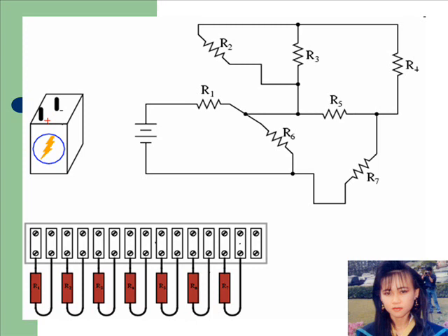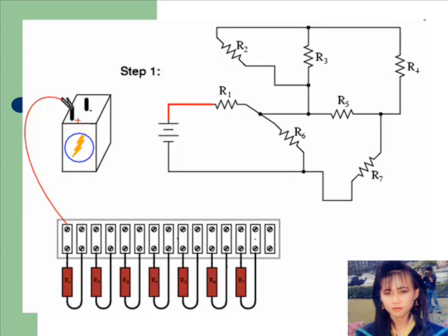First, begin by installing and labeling all resistors on the strip. The original schematic diagram will be shown next to the terminal strip circuit for reference. Next, begin connecting components together wire by wire as shown in the schematic. Overdraw connecting lines in the schematic to indicate completion in the real circuit. Watch this sequence of illustrations as each individual wire is identified in the schematic, then added to the real circuit.